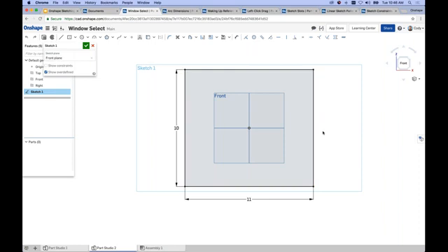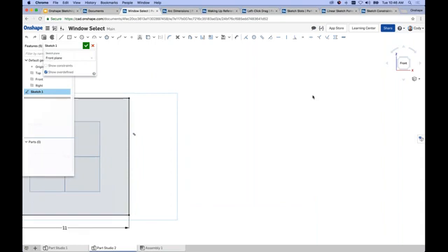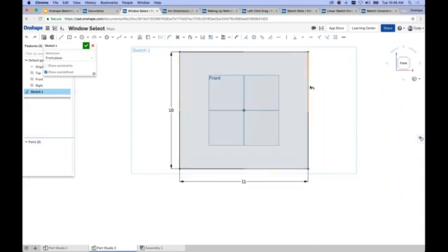My tip is if you mouse over the geometry, it highlights those constraints. The constraints appear as little flags. If you hold down Shift, it doesn't matter where you move your cursor. That constraint will always be visible on the screen as long as Shift is being held down. It's really useful if you need to select other things, or if you need to move your mouse around to get to the flag to delete it.